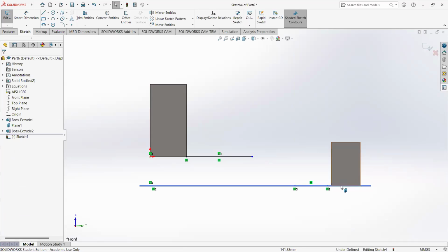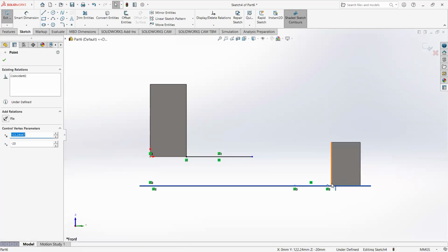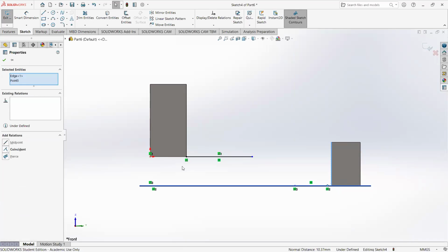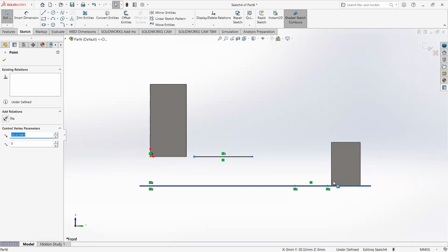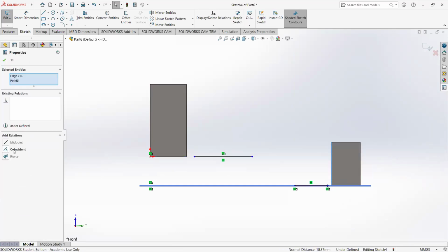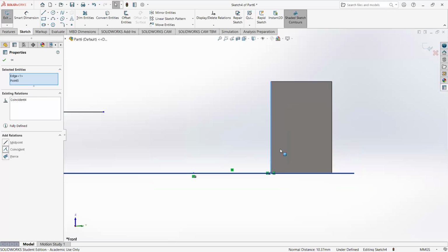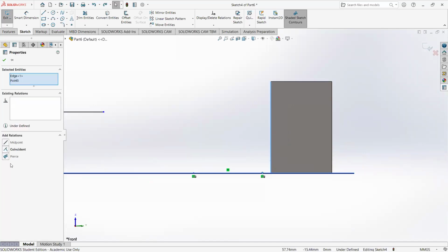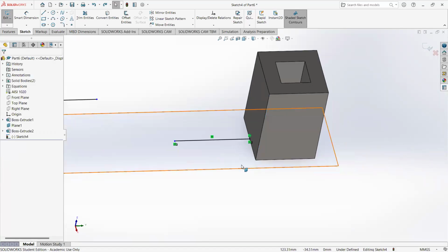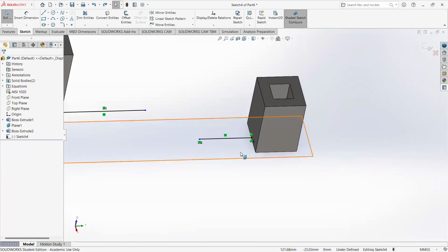We want to grab this point and make sure of the relation, because the plan is to sweep. In this case, when you're going to sweep, it is better to use, if I hit coincident like I have been, I'm on that line. Sometimes that is not good enough for a sweep. Sometimes a sweep wants a pierce. Oh, okay, so we don't intersect, so we can't do the pierce. Occasionally, the sweep will make you do a pierce instead of a coincident.